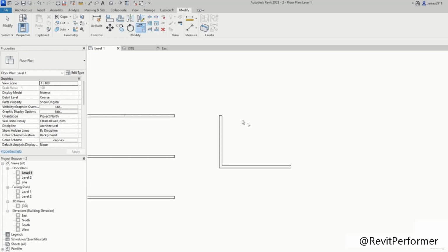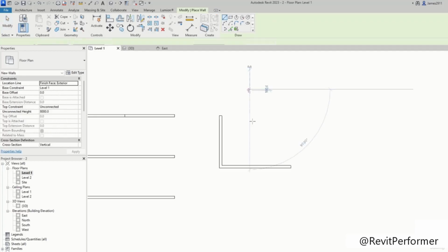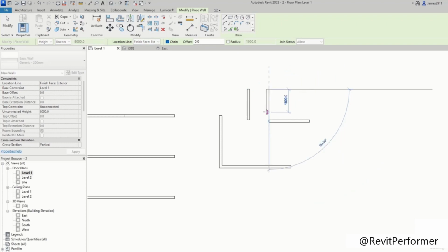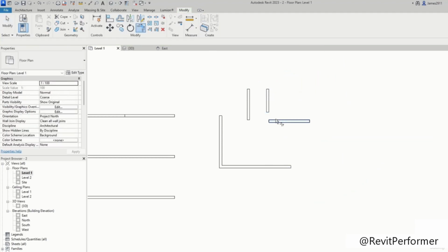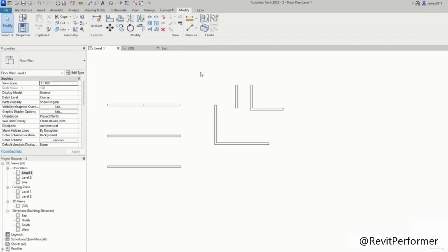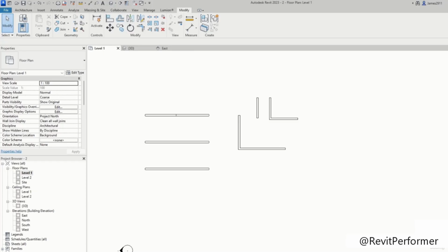Oh, okay. Wait a second, sorry. So I go like this. Here we have a trim and extend. I click on it and I select this wall. The walls will automatically be joined together through this. Like if we have something like this, like this, like this, I click on it and we do that. We also have some more tools here, like the array and scale, which we will learn about in a different lecture.